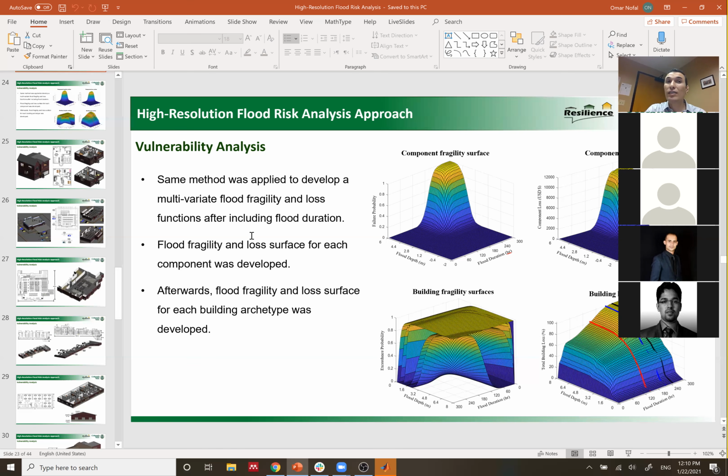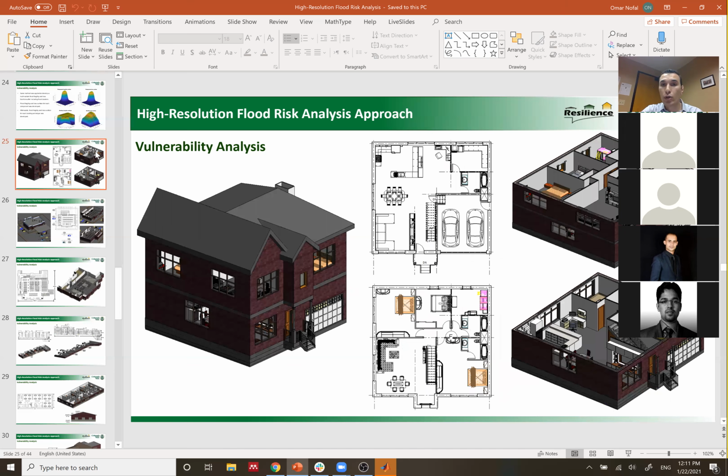And actually, this archetype set is completely different from the one in the Middle East, in Egypt or Jordan. If we go there, there are no wood buildings. Most of them are reinforced concrete buildings. So we need to develop archetypes for reinforced concrete with zero structural loss, because concrete will not be affected by the water that much, unless there is foundation scour or something. So we need to look at the foundation. So that's my answer for now.